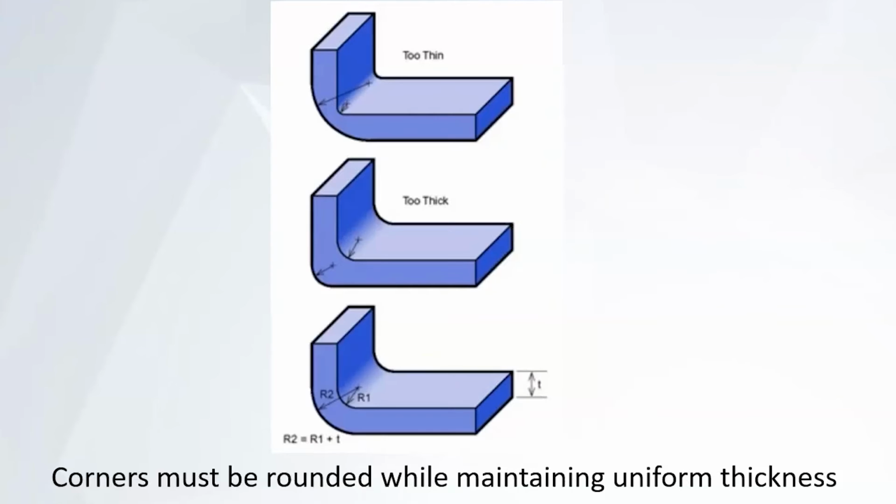In addition to maintaining uniform wall thickness, the other thing you want is you don't want straight edges. You don't want 90-degree turns, because the plastic has a difficult time filling in that corner and making a really sharp corner. Instead, what you want to do is add a chamfer or just round the corners, but you need to round it where the wall thickness remains uniform.